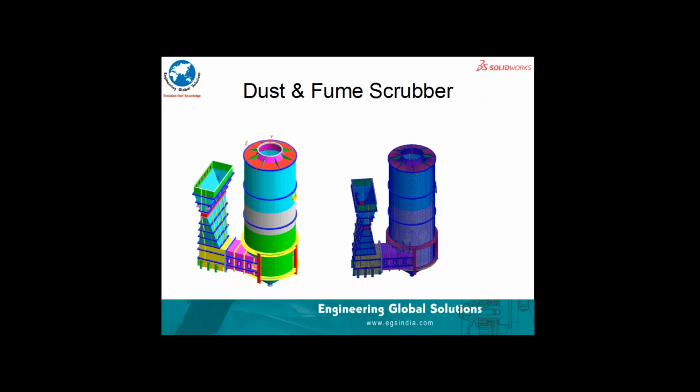The ASME standard is silent about rectangular to circular connections, transitions, as shown in this picture. We found up front that this equipment, which is 25 meters tall, would fail the hydrostatics test and the seismological loading test. Up front in the design, changed the design, improved it, and released it into the marketplace, and this is working in Africa even as we speak. This is things gone right, first time.